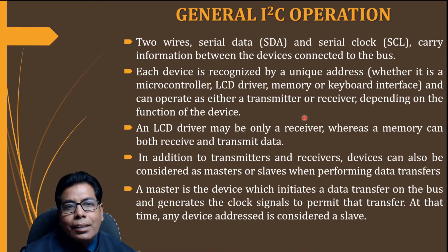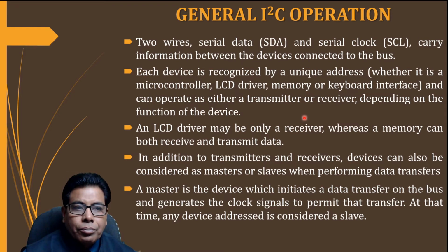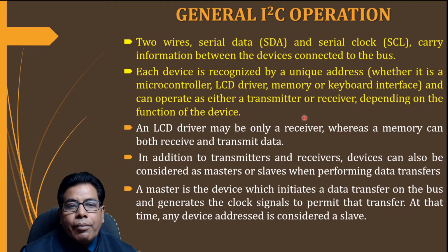So, general I2C operation. Here we have 2 wires, SDA and SCL, data and clock. They will carry information between the devices connected to the bus. Each device has a unique address and will be recognized by that address.